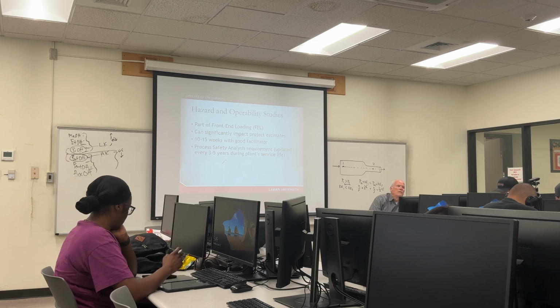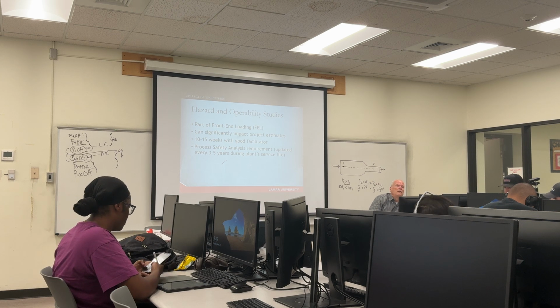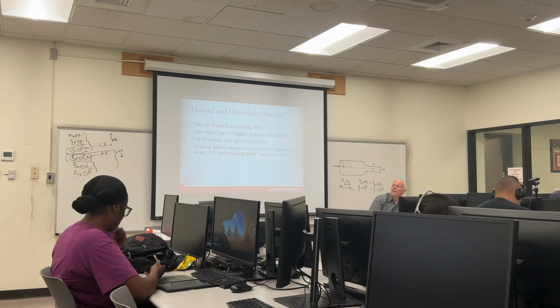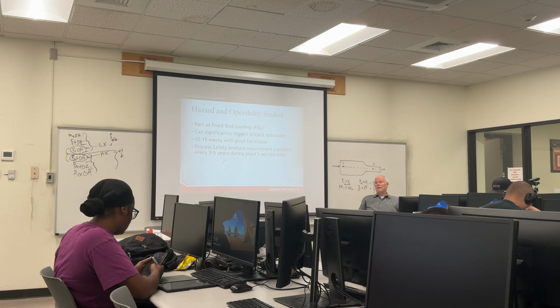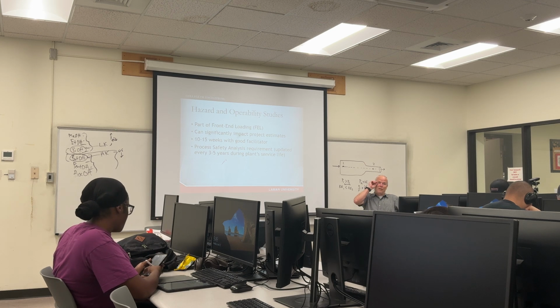Deviations from the design. What you're trying to do is figure out what scenarios exist that could cause bad things to happen. So you're actually considering scenarios. You actually create new scenarios in a HAZOP. These can take 10 to 15 weeks with a good facilitator for a unit.